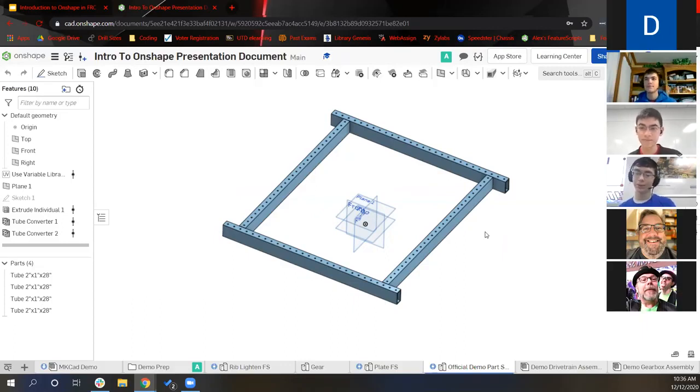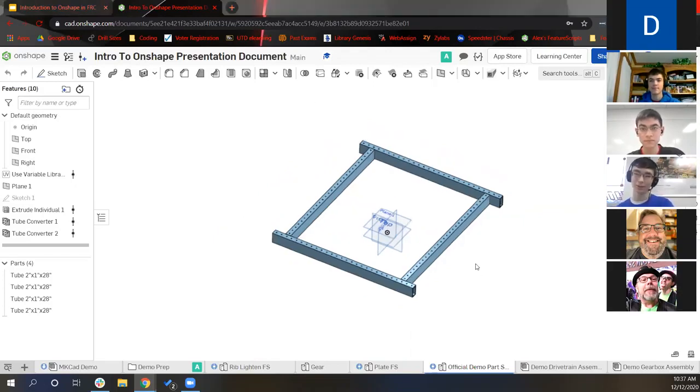So actually, we still use the Inventor HSM or Fusion 360 because it is free with the educational licenses. So what we do is when we have a part that we want to use with the CNC, we download it as a generic step file and import it into the other software. And from there, use the HSM tools there that we're familiar with and generate the G code that we use on the CNC machines. It's not the best process, but it's one of the very few downsides to OnShape. But once you have the part that you're ready to CNC, you probably shouldn't really be modifying it right before you're about to CNC it. So.